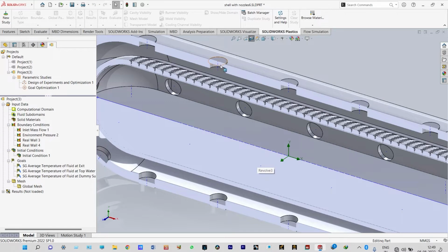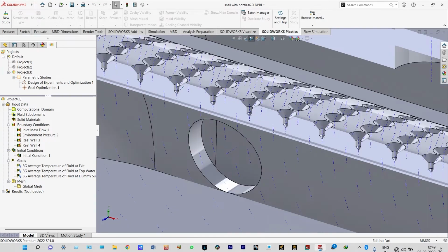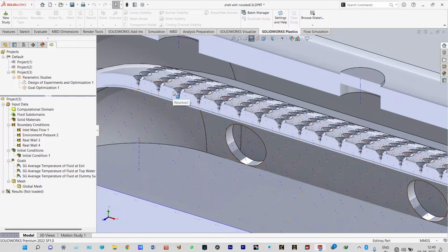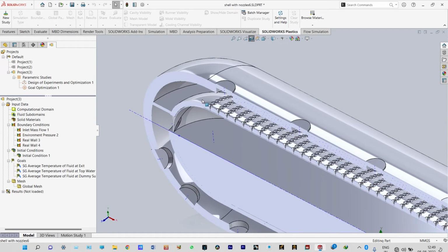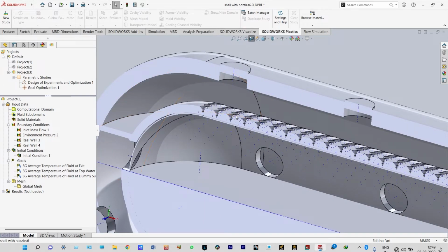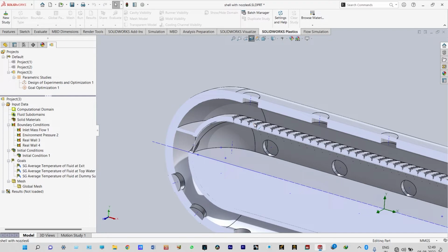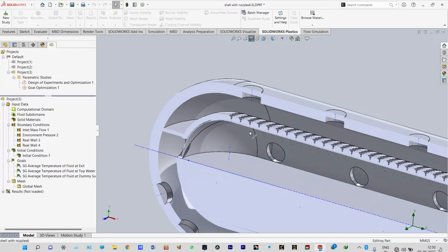This is the top shell, and from this top shell we are providing water at a normal temperature and high pressure, which will be injected through these nozzles. There are a specific number of nozzles surrounding this inner shell up to an angle of 120 degrees, right? From these nozzles we provide normal temperature water at high pressure, injected inside this tank. The tank already has water at 100 degrees centigrade. The bottom part of this tank is filled with water, and the top part is filled with air.